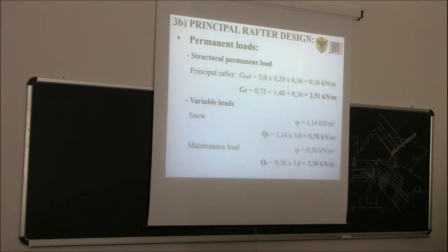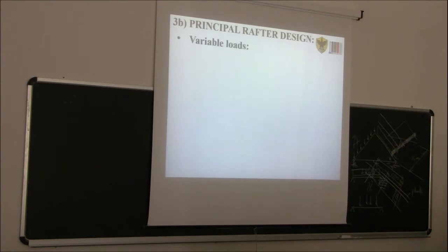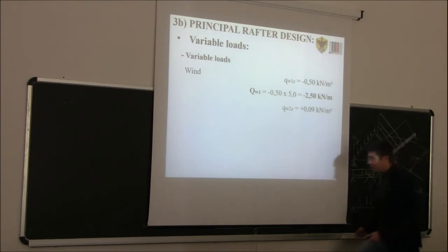Maintenance loads, exactly the same. And for the wind, we have these two loads. So minus 0.5 means that we have the wind which is uplifting the structure. So minus 2.5. Again, with the wind there is this problem.